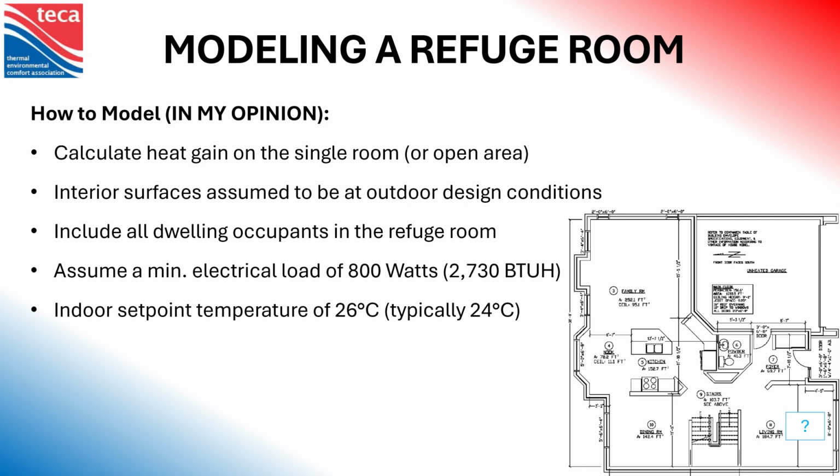And then I take all of the interior surfaces and I assume that they are at outdoor design conditions. I'll include all of the occupants in the dwelling in that refuge room. I'll assume a minimum electrical load of 2,730 BTUs. And then we'll apply the 26-degree indoor set point temperature per the code requirement.